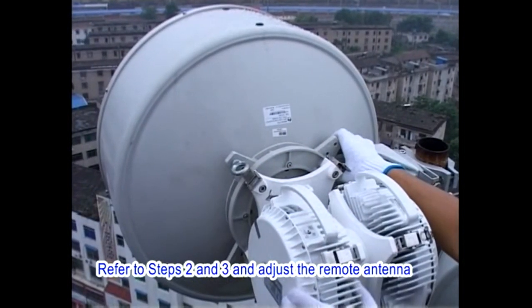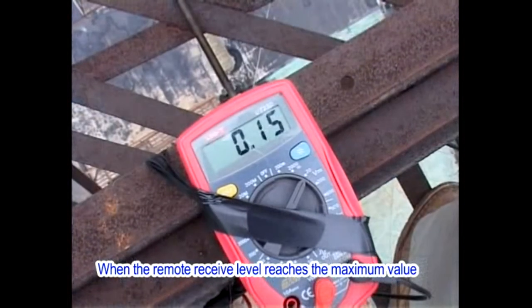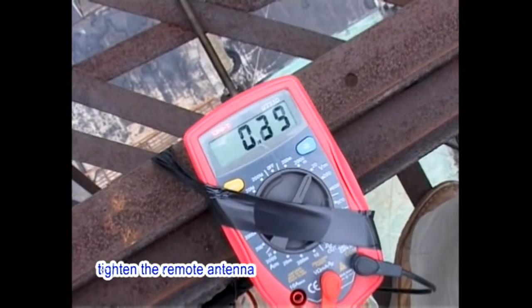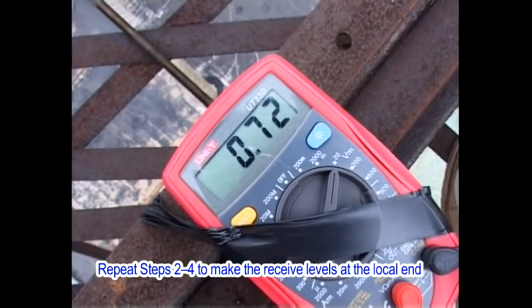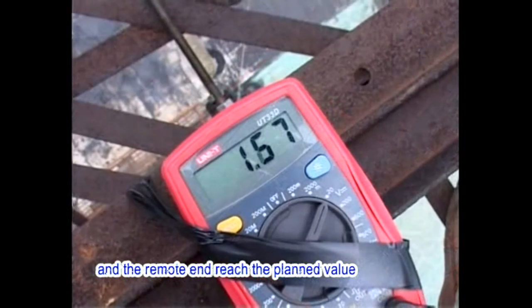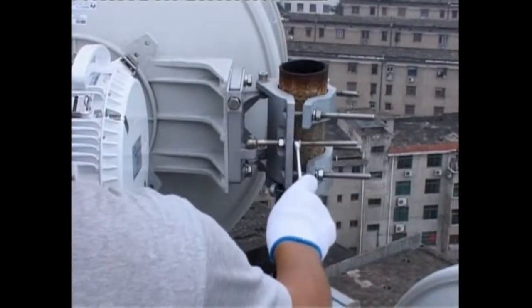Refer to steps 2 and 3 and adjust the remote antenna. When the remote receive level reaches the maximum value, tighten the remote antenna. Repeat steps 2 to 4 to make the receive levels at the local end and the remote end reach the planned value. Tighten the antennas at the two ends.